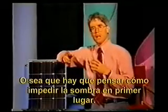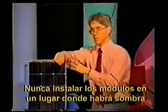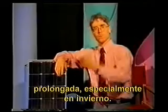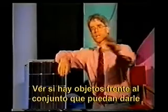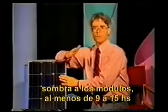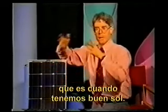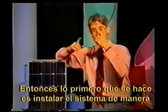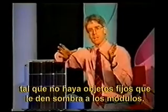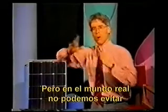So the first thing that you should have in mind is how to prevent shading in the first place. You should never install your modules in a situation where, especially in winter, when the shadows are going to be long, there are any objects in front of your array that are going to cast shadows on your modules, at least between the hours of 9 in the morning and 3 or so in the afternoon when we have good sunlight. So the first thing you should be doing is installing your system such that your modules are not getting shading from fixed objects. But in the real world, we can't avoid all types of shading.